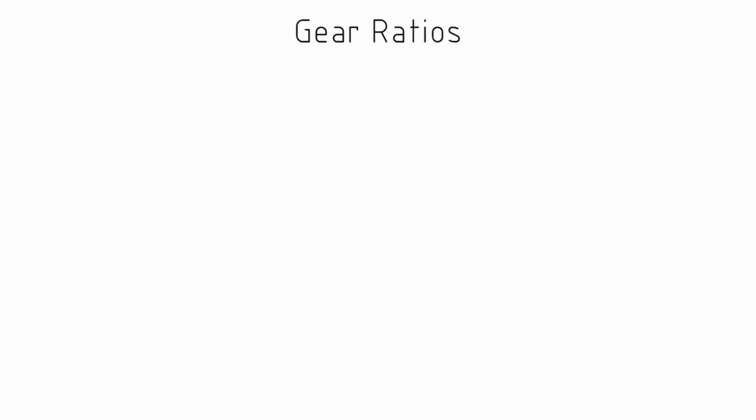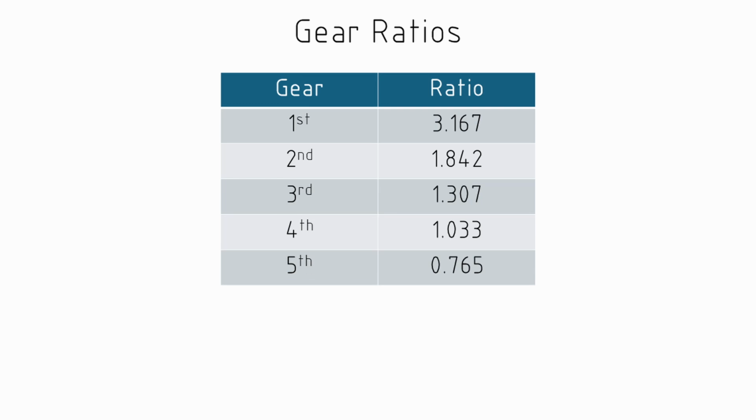We'll also need the gear ratios for the car, and these are usually easy to find on specification websites. You'll see we start with a fairly high ratio for first gear, and then often that fifth gear or final gear of a vehicle is really a cruising gear and has a much lower ratio. With this, we'll need the final drive ratio as well, and the final drive ends up being one of those things for a lot of cars that you can change independent of the gearbox and enables the whole gear chart to either increase the rate of acceleration or decrease the rate as desired.